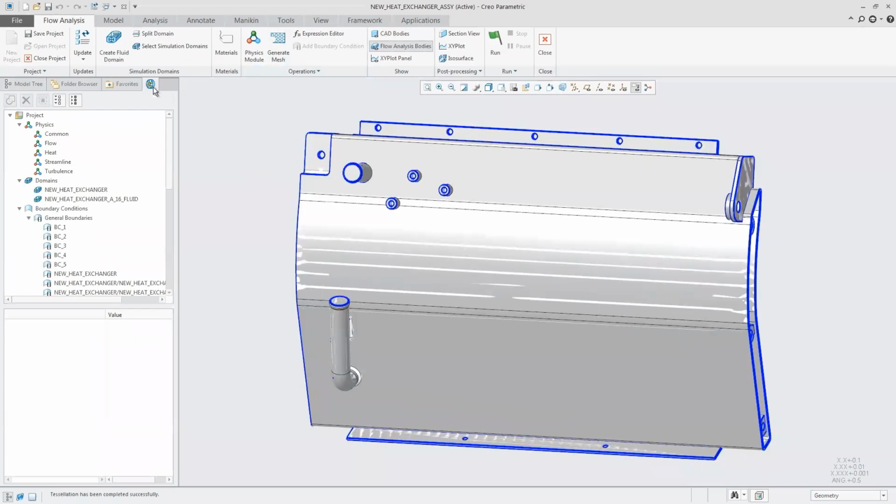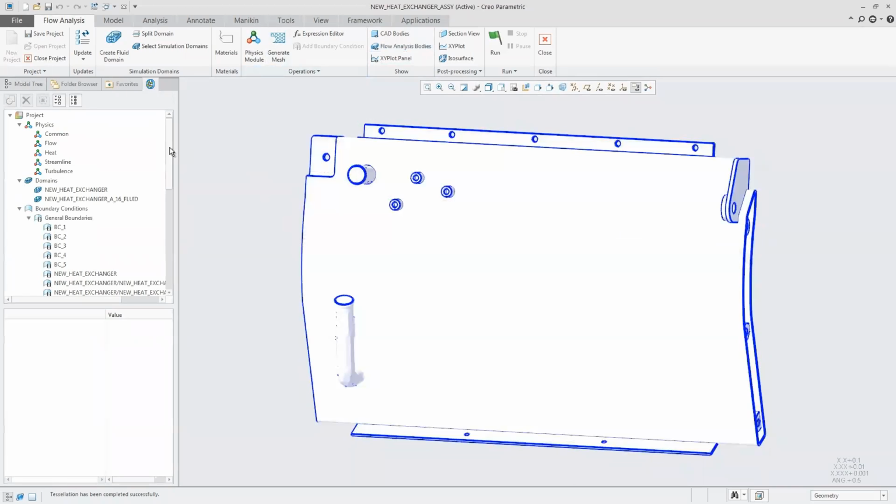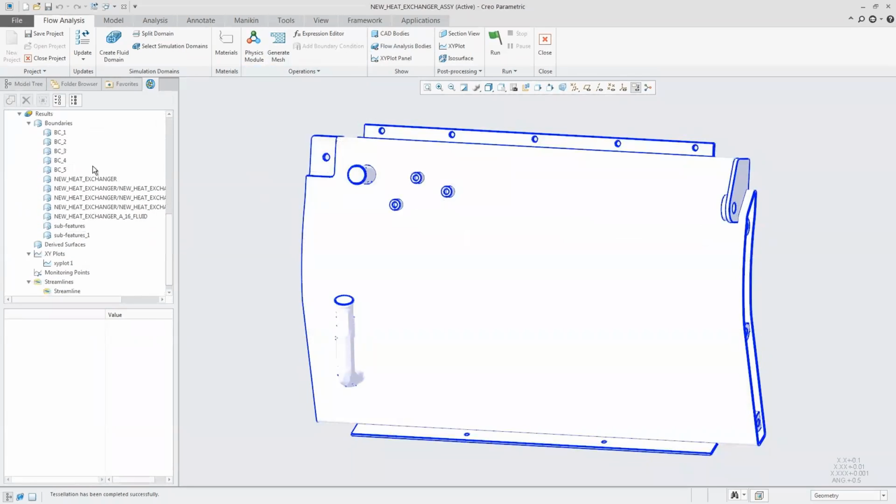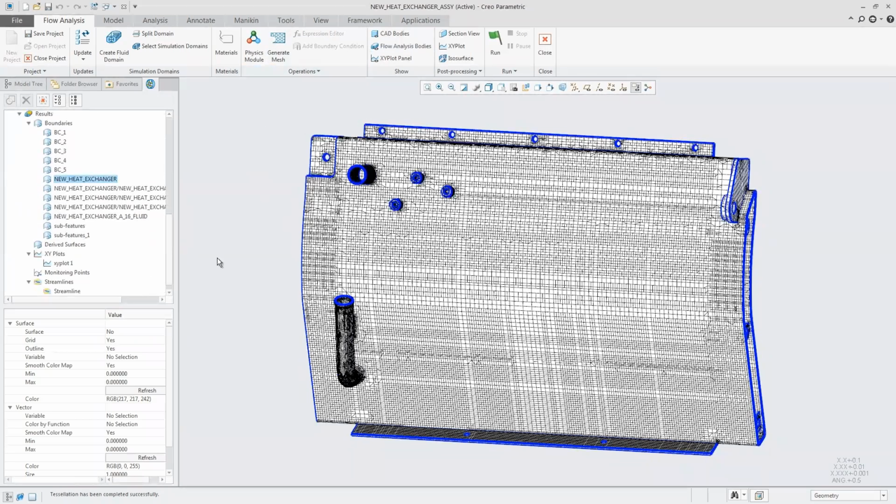And we can simply just open up the grid to check that out and make sure everything looks exactly how we want it to. So it makes that process very easy of building out this mesh here. And taking a look at it, you can see in some of the areas where it's a little bit flat, it'll spread out. It's a little bit more coarse of a mesh where it doesn't need that level of detail. And then maybe in some of the areas where you see more curves or you see a little bit smaller areas, it's going to make that mesh more fine, and we're going to get more refinement in those particular areas for the mesh. But in this case, I'm pretty much happy with that.